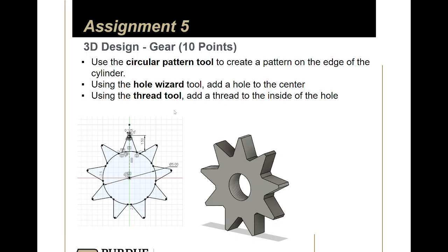Or you could use the hole wizard. So a lot of CAD programs have some kind of hole tool or hole wizard, and it allows you to select standardized hole sizes, or you can even make custom hole sizes. And you know, there is some benefit to using it as a designer because it saves you some time.